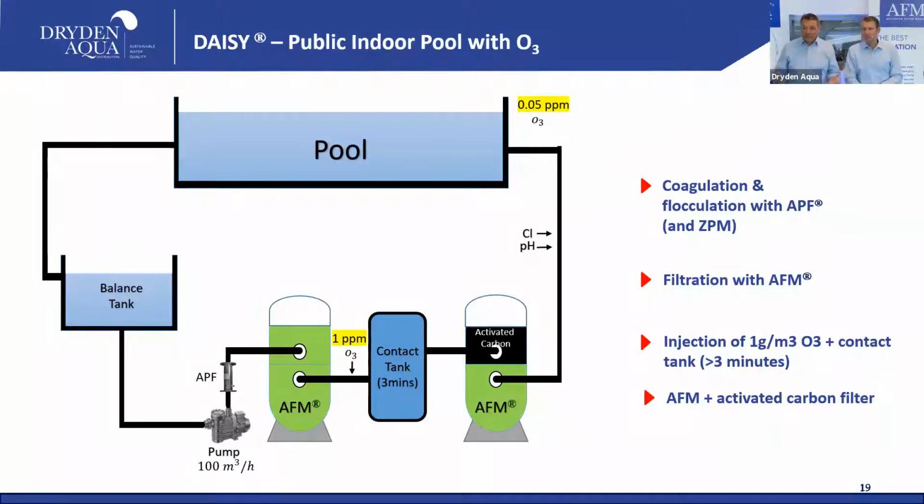But it's a good solution. It's a very expensive solution. It will give really good water quality on the THM values as well as on the combined chlorine values. There is a little bit of risk of biofouling of the carbon, especially if you have too much carbon, but it's very costly. So yeah, good solution. And you also can leave this filter out and just make an ozonization reaction tank and then activated carbon. That's a little bit cheaper, but really the costs are in the ozonization system.